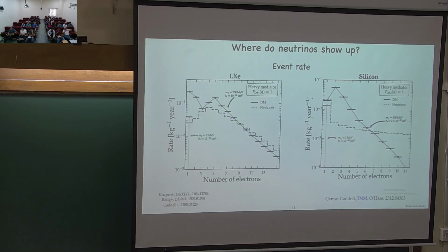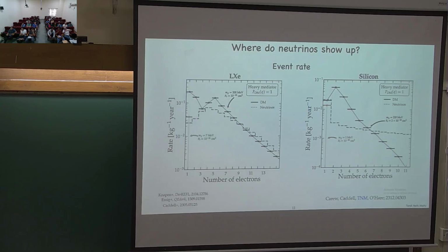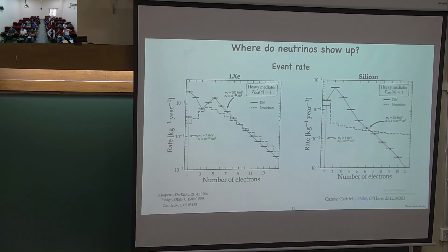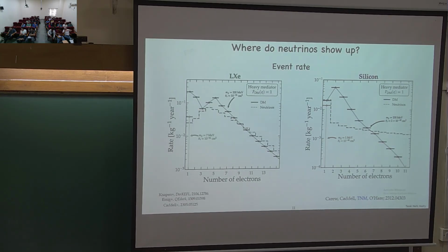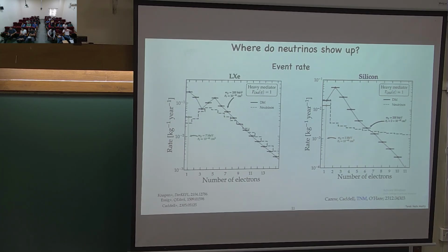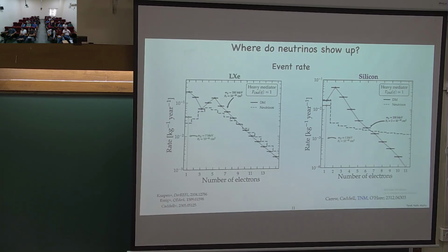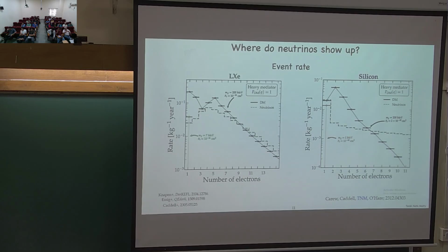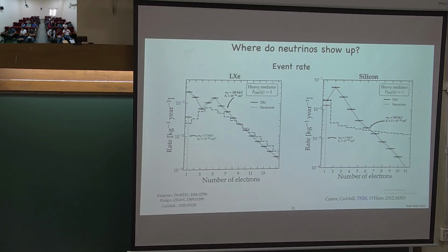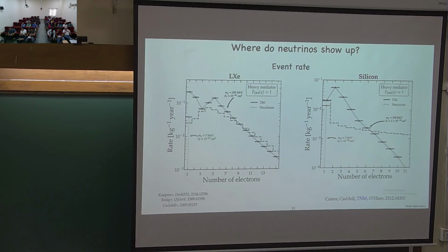That I think I cannot say right now. There are several difficult things that appear over there. But for silicon, once you produce a recoil energy which is above your band gap, you are going to produce 1 electron. Now there is some mean energy for which you can get another electron. So once you cross that particular mean energy, you are going to produce 1 more electron. Something like that.